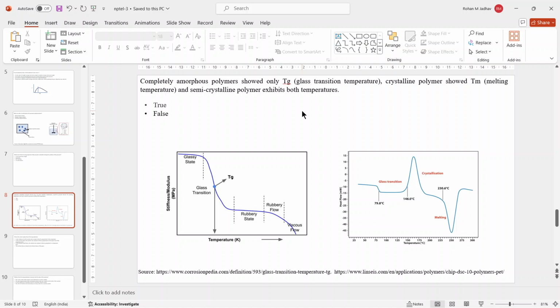Because of this, individual lamellas will form spherulites. So when you have an extremely highly crystalline polymer, as you increase the temperature, the packing factor and the secondary forces are strong enough that the polymer does not react that much to the increasing temperature and it directly melts.